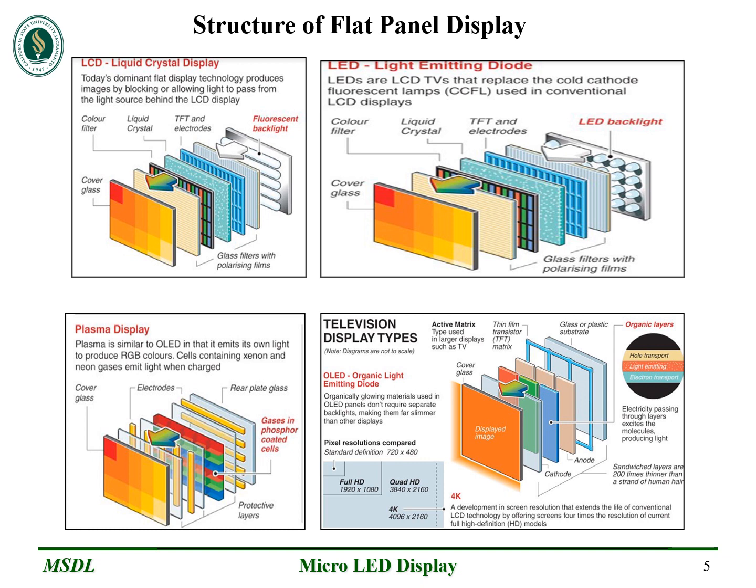Plasma displays have turned out to be a valued option over time. They have excellent black levels because instead of relying on a backlight with a screen in front of it, the plasma display actually outputs its own light. You get extremely fast response time, making plasma great for gaming. The disadvantage of plasma is that compared to a high-end LCD or LED display, the colors can be a little bit washed out. If you are in daylight or a bright environment, you don't have to be in a dark home theater to watch it. And because the front of the display has to be glass, they tend to give a fair amount of glare, making it more difficult again.